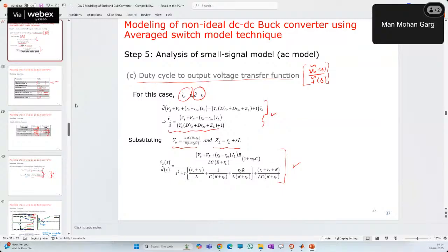That is for the load current to output voltage case, right, sir? Yes, three cases. But for controller design, we don't use the first two. For controller design, we use either V naught upon D, or maybe I L upon D if we are going for current control. But then what is the use of V naught by I naught? Analysis purpose: how much variation could be there, how much disturbance rejection there is. This also I will try to cover in control systems.